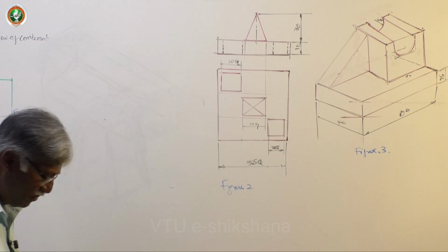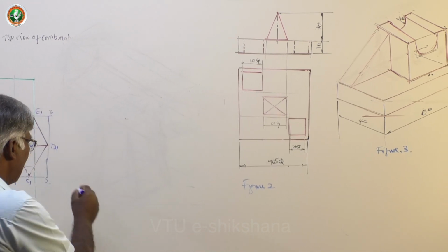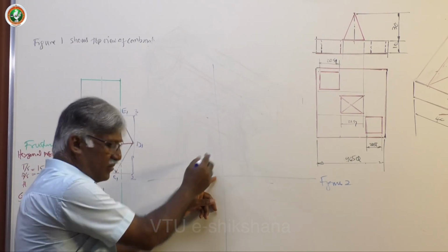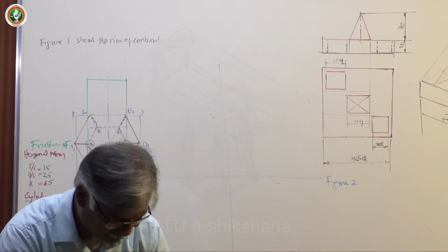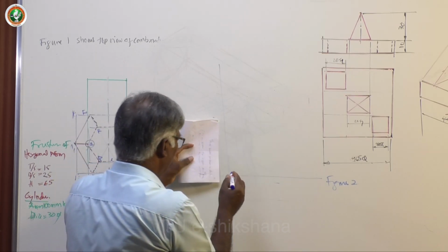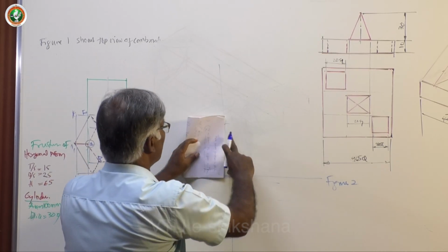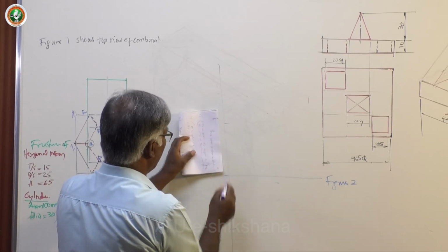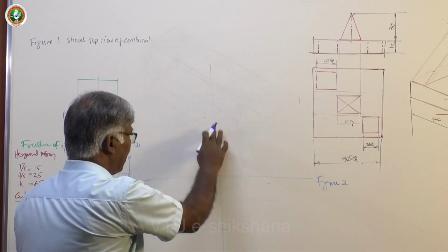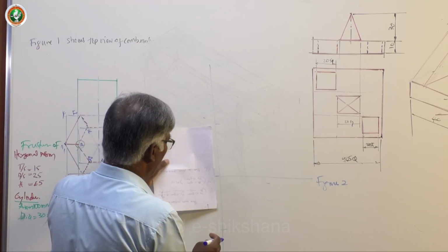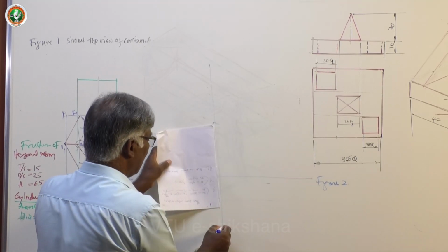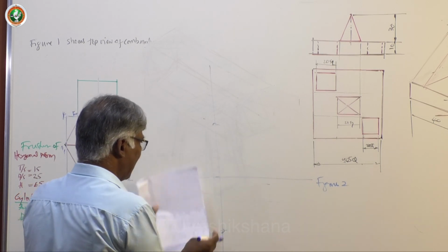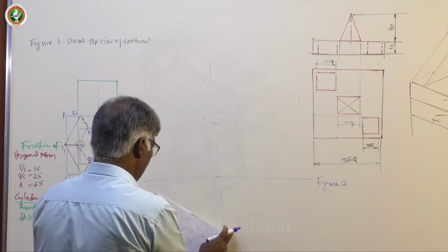Very easy job for us, the plus mark method. Take 45 with the compass. From this center draw arcs, so one arc and a second arc. Then take the total of this, and with the compass placed here, don't lift the compass. Take the total distance here and draw an arc.